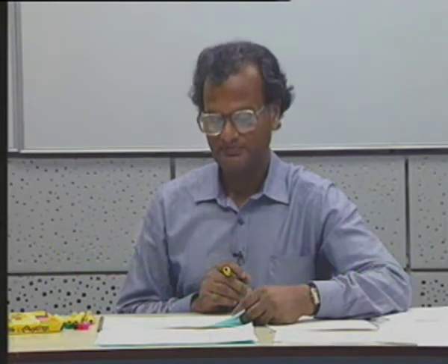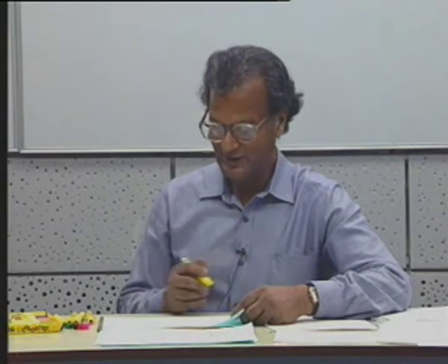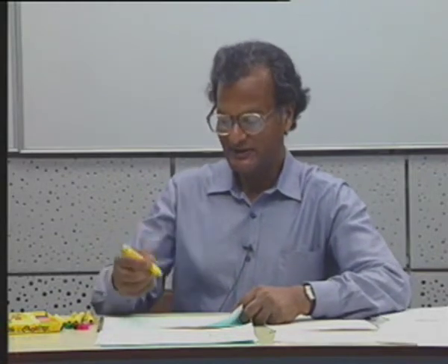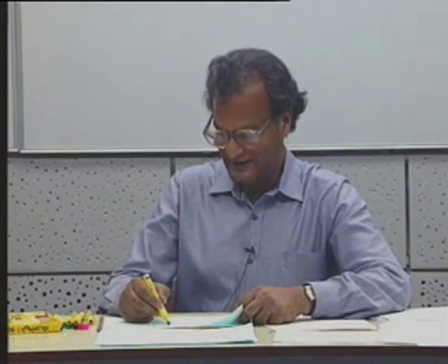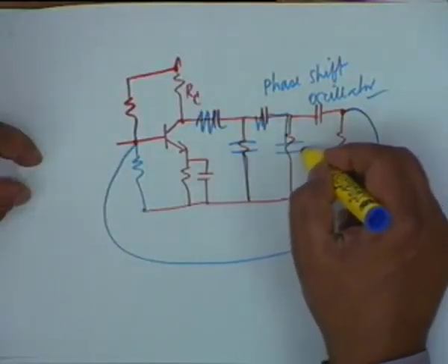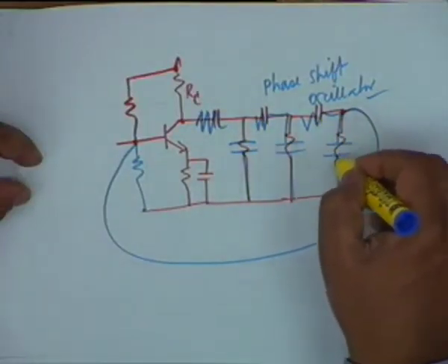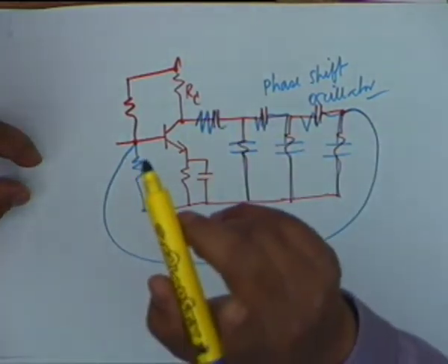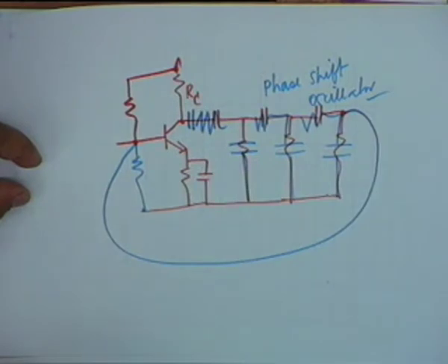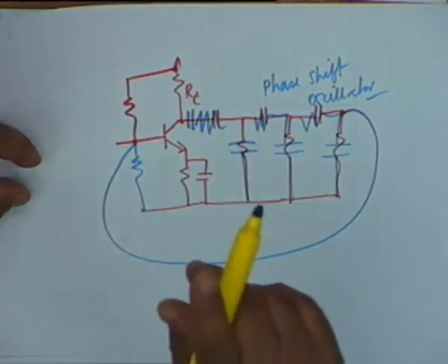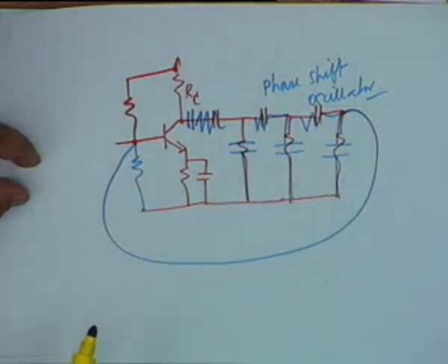Right. Correct. We can do that, we can do it that way also. If that satisfies Aditya, what we shall do is we will use an R here and a C here. It gives the same result, except that we require an extra capacitor here. Isn't that right? Because otherwise you cannot block out DC. That is why the CR circuit is preferred.